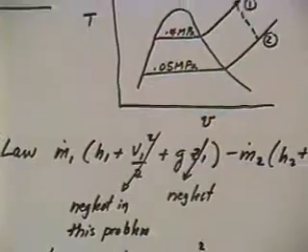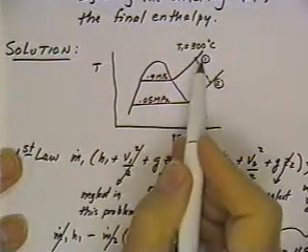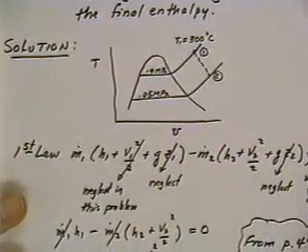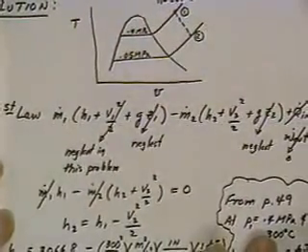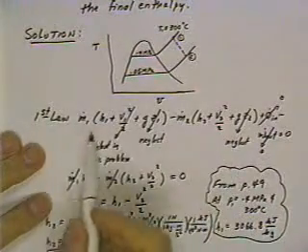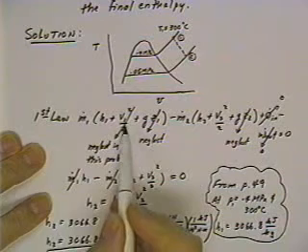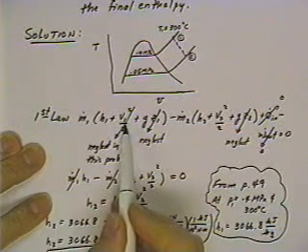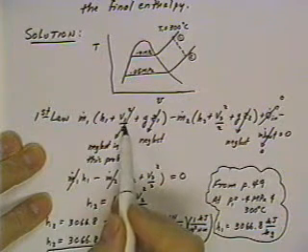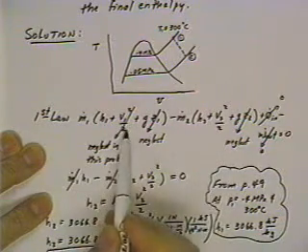Okay, so we can go back to our little graph here. We know that we are at 0.4 of a megapascal. We just calculated the enthalpy here. Let's go to our first law equation. First law equation then, we're throwing out entering kinetic energy. Now this term would not necessarily be thrown out in all cases, but we're given that the entering kinetic energy is small compared to the leaving, so therefore we can neglect that.